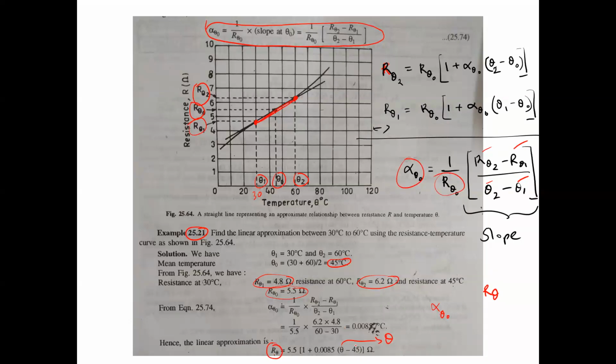On the other hand, suppose your goal is to determine the temperature theta, then you can determine the resistance R using some mechanism which can be even by measuring by Wheatstone bridge. And once you know the resistance, then you can easily solve for the temperature as well.